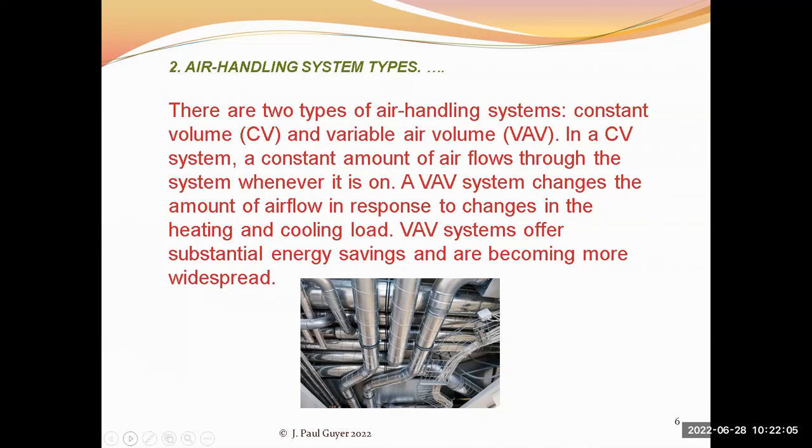The newer systems, and they have been the industry standard, you might say, for 2 or 3 decades, are variable air volume systems. And with variable air volume systems, you have the air being pushed into the ducts, and there are a lot of ducts often to serve different spaces.